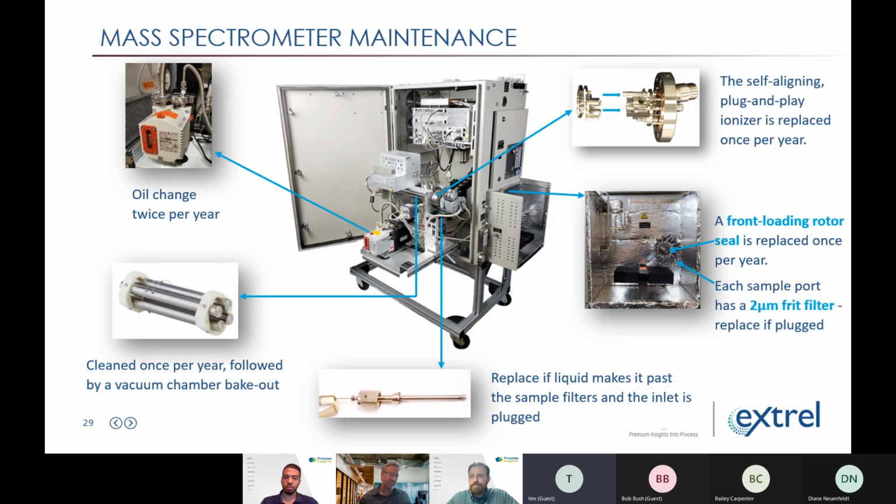So kind of like what you're saying is, there are meters with much higher turn down ratio, which is part of some of the solution out there also. Are you using the old orifice type meters, or are they newer meters? We already had orifice plates in our flare.